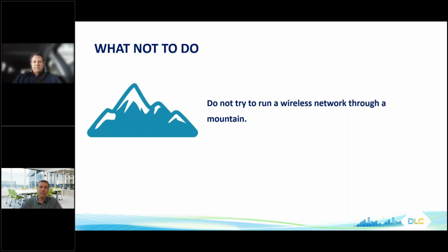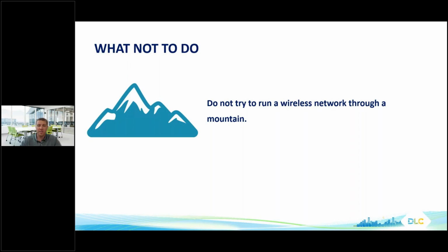On a smaller scale, whenever you're doing the plan, you should have somebody who's familiar with the site and somebody who's familiar with the NLC system. I see a lot of just not understanding range and how that impacts it. A lot of subtleties like that, where many systems have their standard device with the standard range, and they'll have a device that has a longer range. And if somebody had said, hey, let's just pop a couple of these long range devices into the system, they would have had beautiful connectivity and a smooth, easy commissioning, and everything would have worked out of the box. But because either the person planning wasn't familiar with the site or wasn't familiar with the system, they have some connectivity issues, and it's just not smooth.